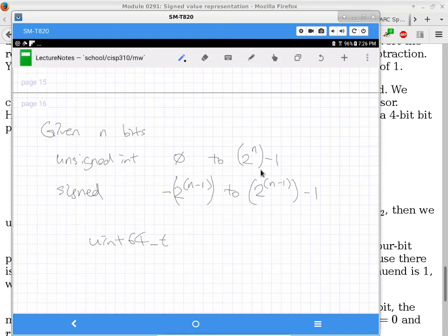Because now we know that's the problem. But at the time, they didn't know that the width could have an impact on the logic of controlling the stepper motor, ramping up and ramping down the speed. So they were looking at different things. They were looking at connections to the stepper motors. They were looking at all the wrong places and spending a lot more time than they really should have to fix that one. So this is going back to, but it works is not always the best thing.